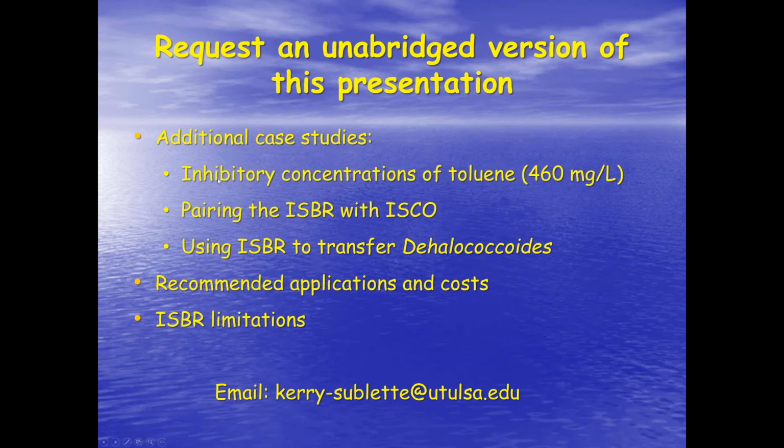One involving treatment of a site with 6 different bioreactors where the toluene concentrations were very, very high, 460 milligrams per liter. That's not a mistake, that's milligrams. Inhibitory concentrations of toluene, where we were able to reduce those concentrations very significantly. A case study where we paired the in situ bioreactor with an ISCO process for treating hydrocarbons.